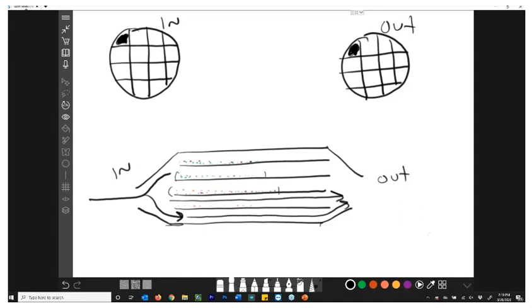Now, if for some reason your DOC assembly was poisoned, as they call it, if we got a whole bunch of carbon or coolant or fuel, a lot of different substances upstream that came downstream, what would happen is a thick coat of carbon would end up covering up these lines of these walls, right? This carbon's just thick, and it'd start lining these walls up. And what happens is if the carbon lines up the walls, well, we can still get some exhaust gas through there, right? We can still get it through this area. Problem is there's no way for it to react because there's no way that it can touch the precious metals.